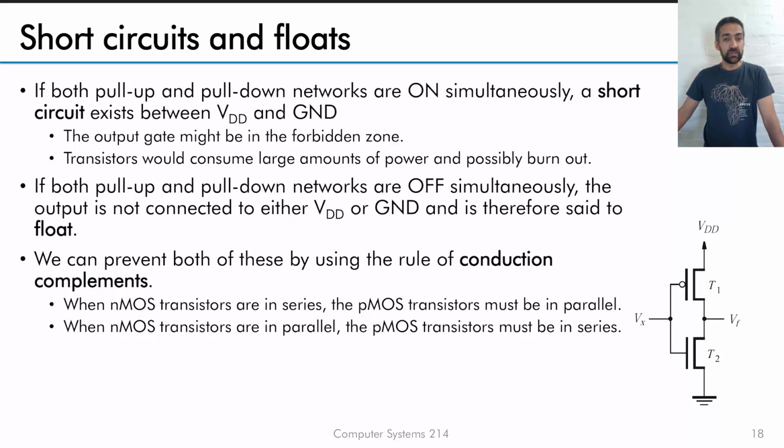We can prevent these by using the rule of conduction complements. When the nMOS transistors are in series, the pMOS transistors must be in parallel. When the nMOS transistors are in parallel, the pMOS must be in series. And that's the logic check that we apply to it.